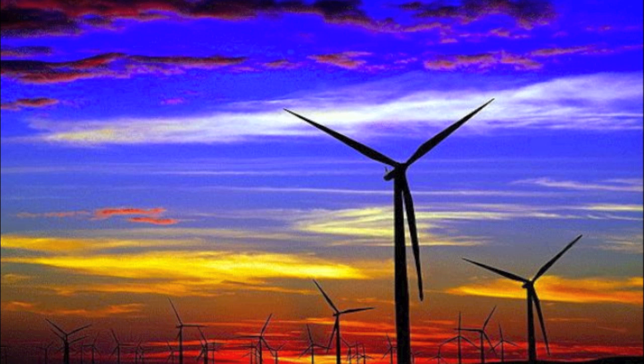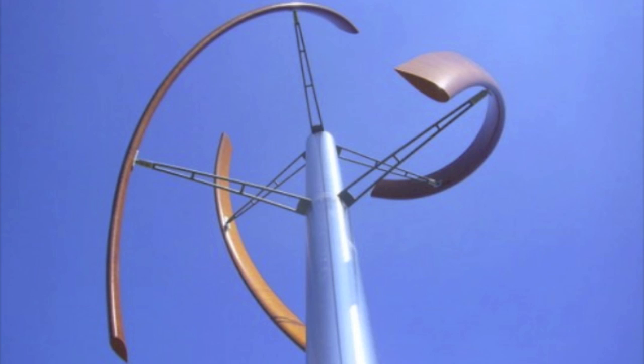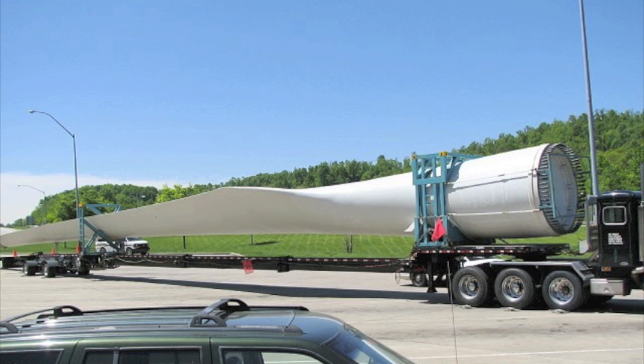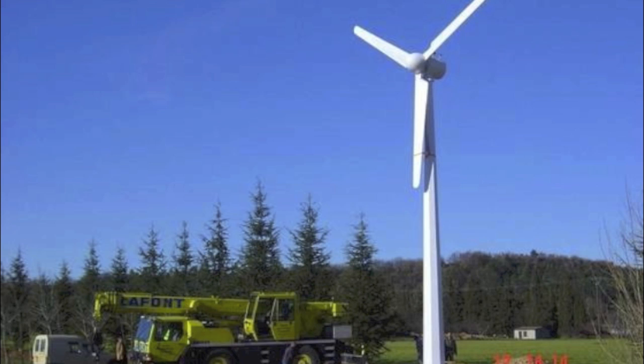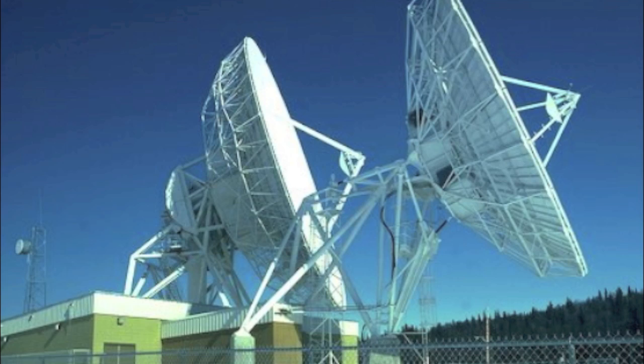A small wind machine has rotors between 8 and 25 feet in diameter and stands upward of 30 feet, capable of supplying the power needs of an all-electric home or small business. Utility-scale turbines range in power ratings from 50 to 750 kilowatts, whereas single small turbines, usually below 50 kilowatts, are used for homes, telecommunication dishes, or water pumping.